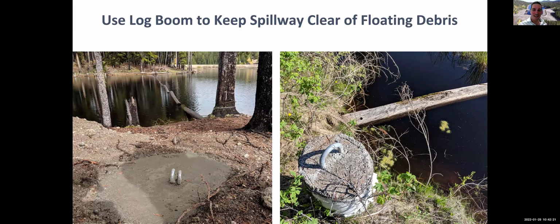Now, we need to manage the debris as well. I had a question about the log boom. Make sure they continue to be buoyant. Keep them connected. The photo on the right, it's not even connected. You might need to replace your anchors. The one on the left is just tied around a tree, which could certainly work. In this case, they're replacing it.